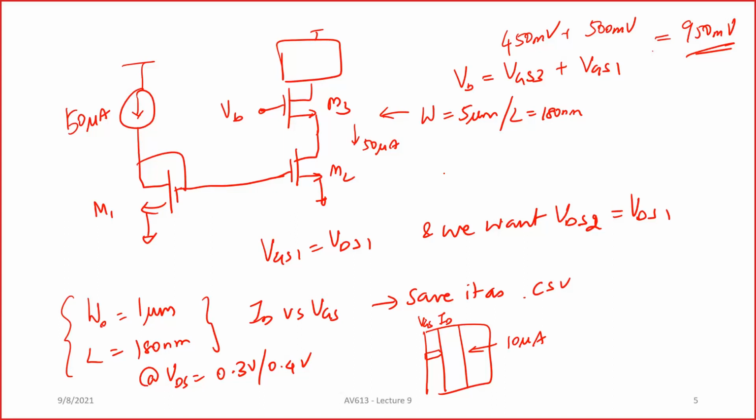All right. So did you understand what I told? For the VGS that you want, the way you calculate is, take the CSV, keep it, and use it as a reference for the rest of the course. Sometimes you might start with the VGS and find out the current and then scale the W by L. Or in this case, you have the current value, and you find out what VGS is required. All right. So that is how you can do.